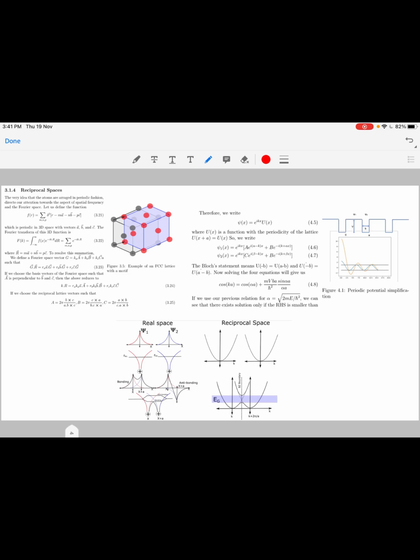And crystallinity means that you have atoms which are periodic in space, and then we have what are called lattices. Lattices are mathematical constructs, and we saw various lattices that are possible: simple cube, body centered, face centered, and so on. The most important for solid state devices was the face centered cube, because most semiconductors tend to form this. If you have a face centered cube with a 2-atom basis, we saw that you are most likely to get the valence band completely filled when you have temperatures close to zero.